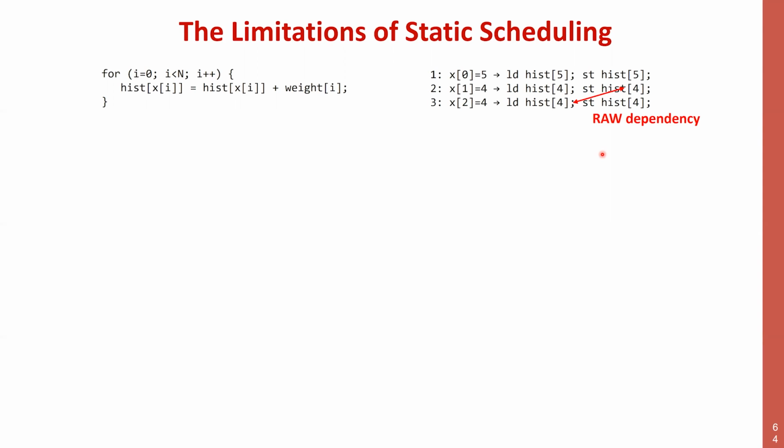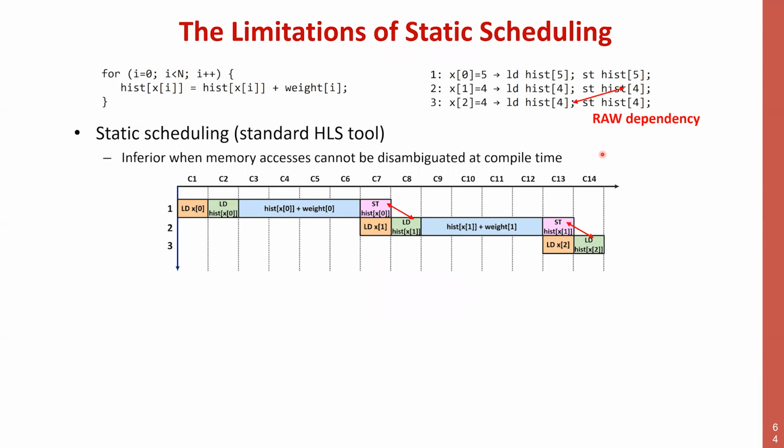If you don't have any special structure like you have in Itanium, and you have to statically schedule this, in other words, if you give this piece of code with whatever optimization you want to Vivado HLS or any of the other classic HLS tools, the kind of schedule that you can obtain is only this one. You have to assume that the load is dependent on the store, because it can be, right? So conservatively, you have to assume a dependency, and you'll schedule it after the load.